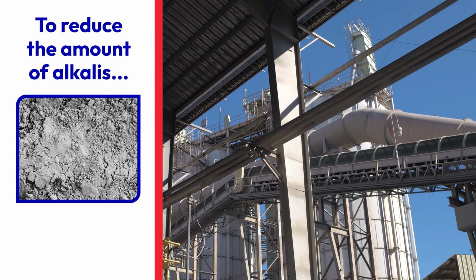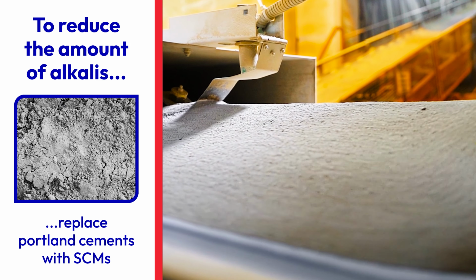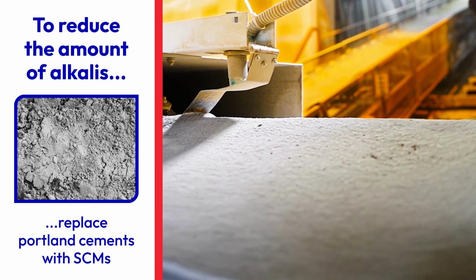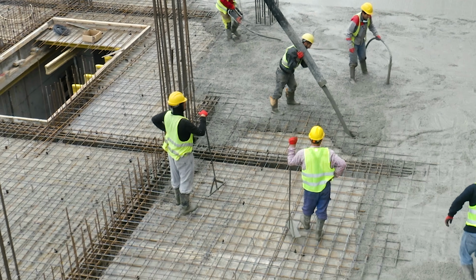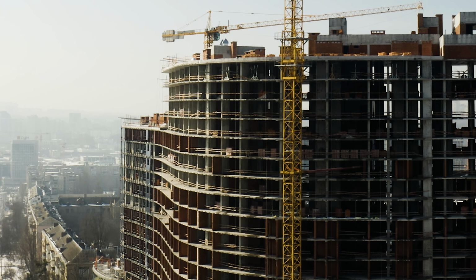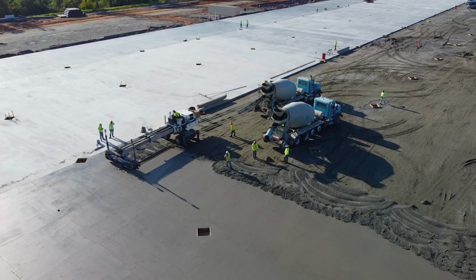The third thing is reducing the amount of alkalis. And so that can be replacing Portland cements with supplementary cementitious materials. The other thing that some of those supplementary cementitious materials can do is they can bind up some of the alkalis in reaction products so they're no longer available.